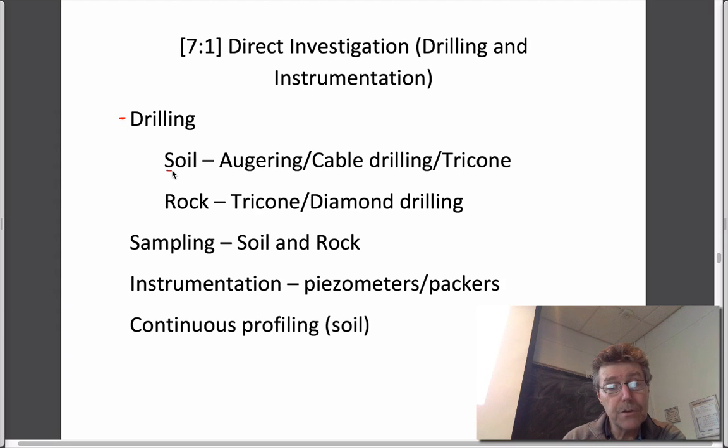and we know that in terms of methods in drilling, it matters whether you're going through soil, in which solid or hollow stem augering is one way to go, or by using just rotary drilling, not diamond drilling, but just rotary drilling, is one way to go. In the case of tricone drilling, you don't get any samples, but you do get chips out of the hole. Also in solid stem augering, you also have to guess. But in hollow stem augering, you're actually able to use the auger flights as the drill casing and sample from inside them. And so sampling is key.